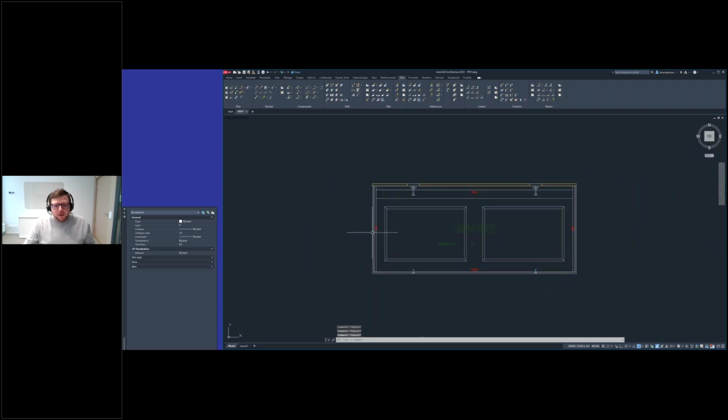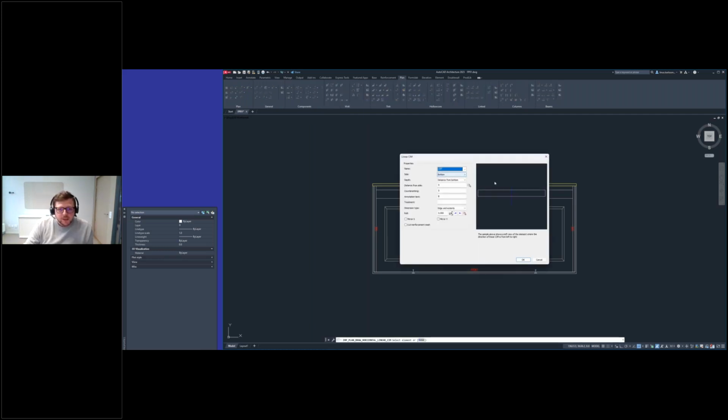Great. Now I have a lot of things, but I'm lacking a few things. So the first thing I'm lacking is the dripping nose, so that the water is handled. That I will do with the feature draw horizontal or draw linear custom material, which was released for slabs in 17. So I have my list shape here. I want to add it in the bottom, no distance or anything, so I say okay.